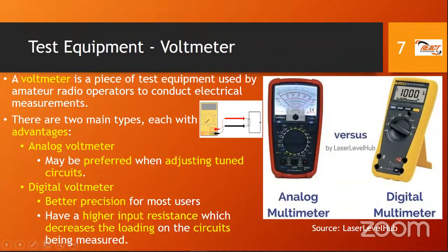And keeping it real, this is what it actually looks like. We have a little diagram here in the middle that shows you how you use it. So you have a circuit here. So you have probably a resistor in a circuit. You have a battery or a voltage source. You have a resistor, and you want to measure the voltage drop across the resistor. This is your trusty meter. You have our two leads. You have your leads across the resistor, and you will measure your voltage, for example. So this is how you actually use your test instrument in a circuit. Our little circuit on the right-hand side, very basic circuit, a battery or voltage source, and a resistor. You measure it using the leads, and the instrument will give you the readout.